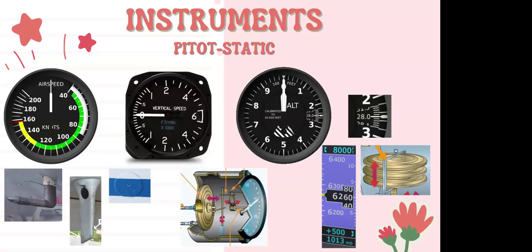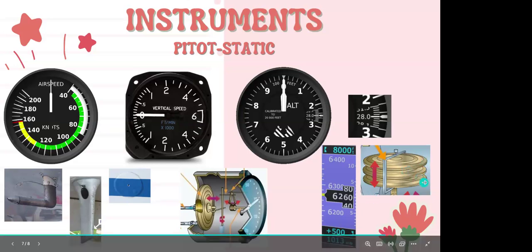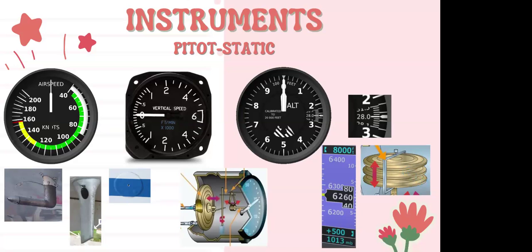So as we go up in altitude, there's going to be less resistance in the case, right? Because we get less dense air, which causes that wafer to expand, which moves the dials on the face, indicating our altitude. But how many times have we really flown on a day where the altimeter reads 2992? Not that frequently, unless you're lucky and picking your days really well. Most of the time, it is a non-standard barometric pressure.